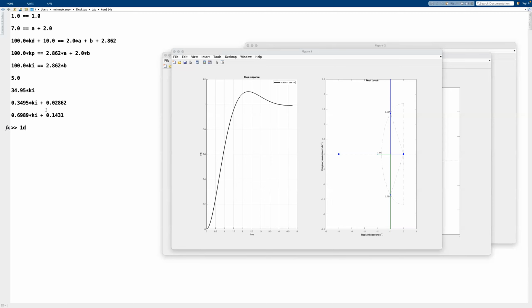But in this case, we are in a 1D space, on a straight line, because we know that it should be positive. So we are basically in an interval between 0 and infinity here, because negative makes it unstable. So we're quite restrictive in terms of search. And this would be the easiest one, because we need an objective function that tells the story about settling time and overshoot, and we should be good to go.